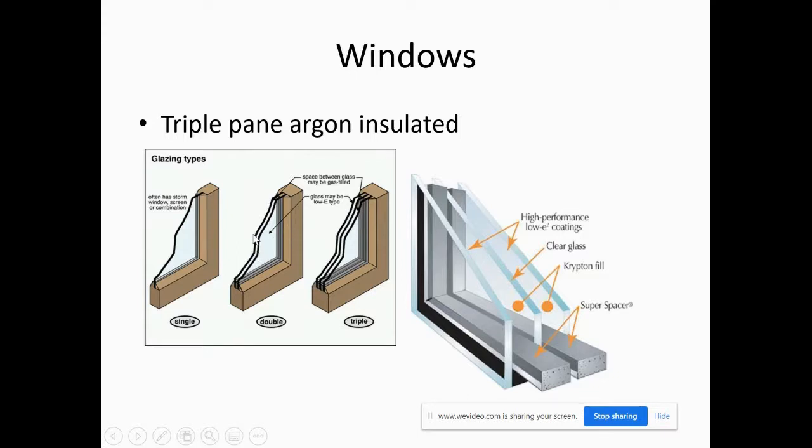So they make air spaces, and they usually go for argon because it doesn't conduct heat nearly as much. Krypton is another gas they like to use, not related to Superman. It's a noble gas. I'm sorry. But these little air gaps help make the windows warmer.